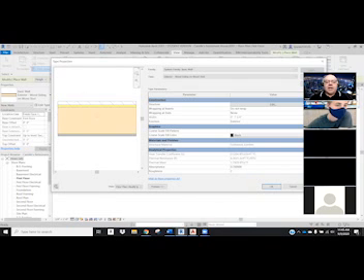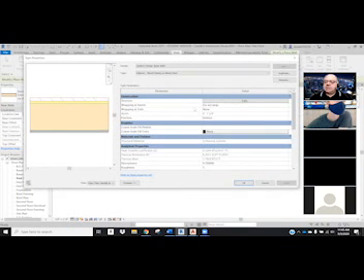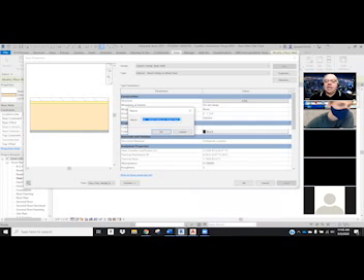Okay, so I know what this wall is made of. Now, when we go into this aspect and we are going to modify a component, whether it's a table or a wall or a door, we always do duplicate. We never change something without leaving the original behind. So click on duplicate, and it's going to ask you to give it a new name.